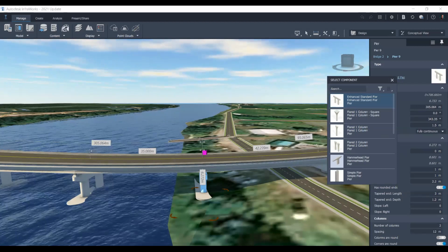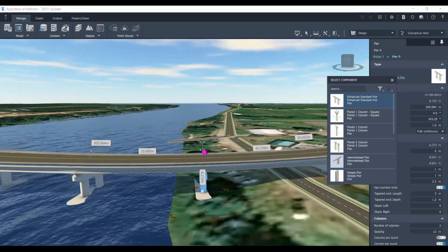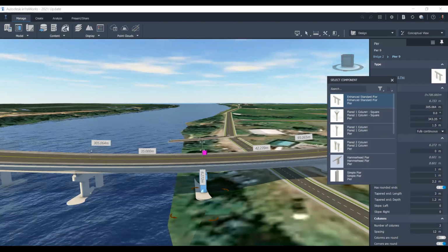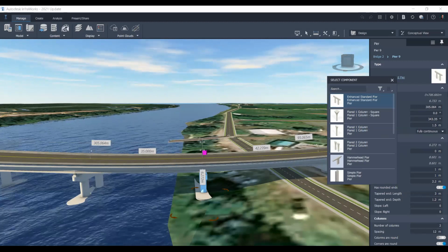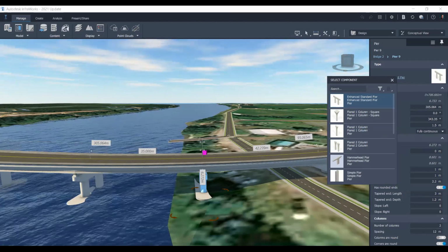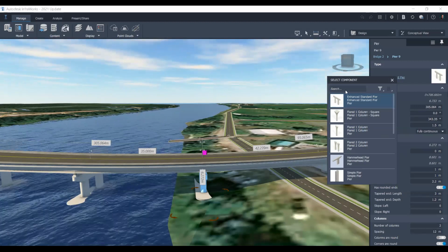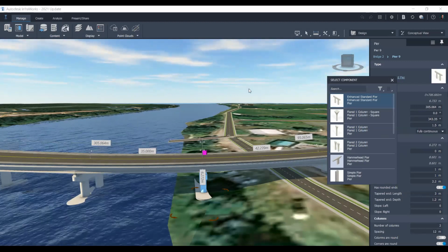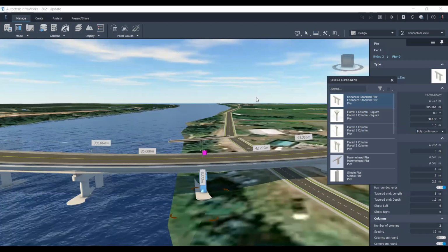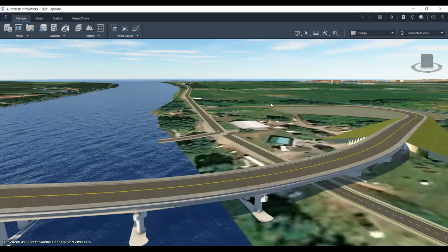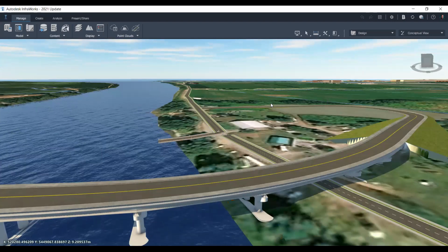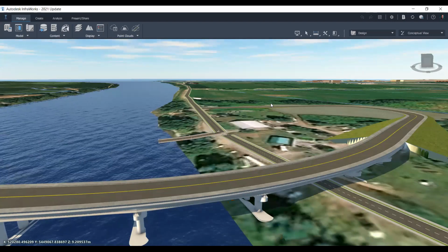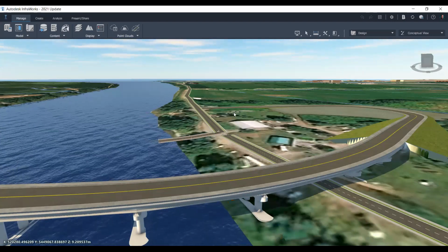This is the selection of whatever kind of pier you want, essentially. The software comes with these piers. But if you are an Inventor user, you can install Inventor and install the InfraWorks Inventor plugin to allow you to create any of this parametric geometry yourself. So with InfraWorks and the Inventor plugin, you can do almost anything you want with this software. You do the right thing in Inventor and save it in such a way that it's compatible with InfraWorks. You can create your own content, not just limited to piers, but lots of other bridge components. Again, I'm not a bridge guy, but it's a pretty interesting feature, I think.